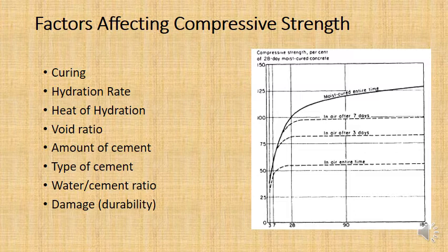It would weaken the concrete. But if you have a very high cement to aggregate ratio, that means all of the aggregates are not going to sit on top of one another, and you're going to have large pockets of the concrete which are basically just cement water paste which has dried.